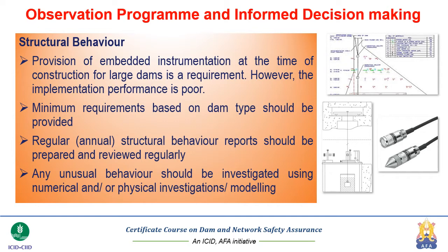Regular structural behavior reports have to be prepared, and they have to be reviewed regularly at the expertise level, where if any phenomenon is developing, then that has to be arrested, or that has to be analyzed and then provided the remedial measures for. Any unusual behavior should be investigated using the numerical and physical investigations and modeling. So observation program becomes an input to such exercises of modeling, which can then work out the impacts of very complex phenomena, and then also lead to development of the remedial measures.